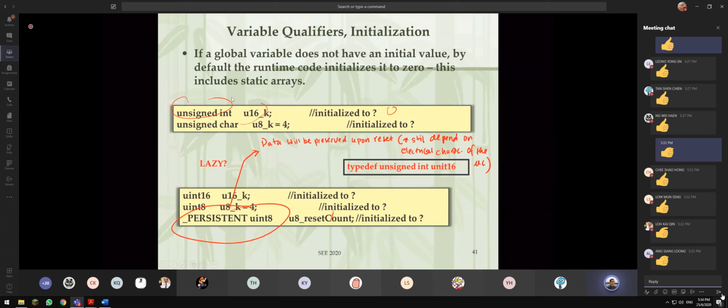So remember or not? That's the reason for Microchip. I'm not sure about the latest version. Ten years ago in Microchip, you needed to type unsigned integer. Later, they changed it. They found that not many people are using negative values because they're using two's complement. So they updated it. Whether you put unsigned or without unsigned, it still supports 0 until 65535. There's no negative. But this is not the case for other microcontrollers.